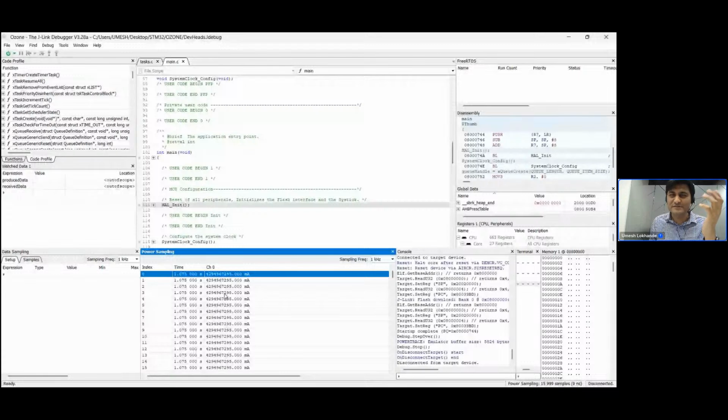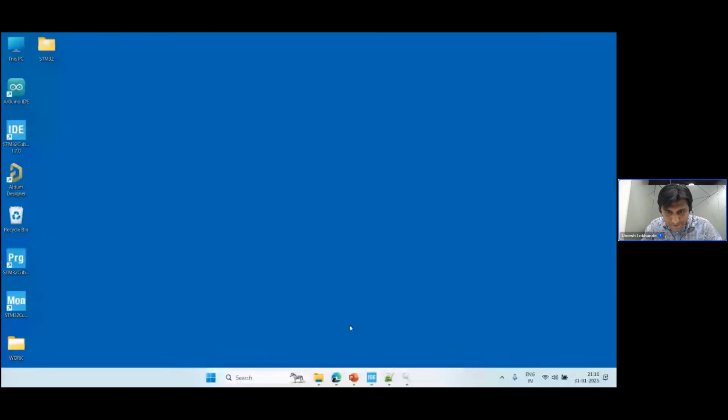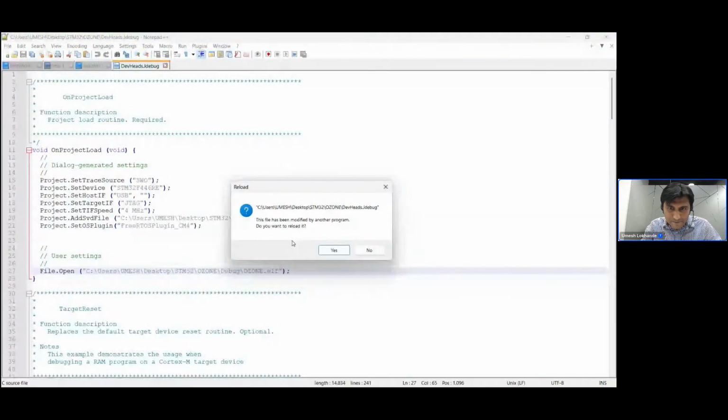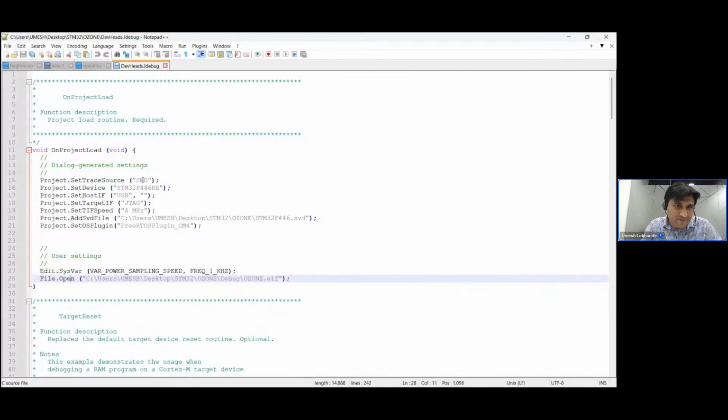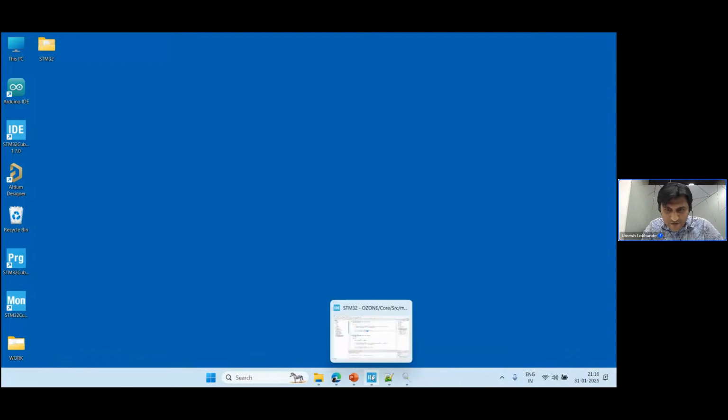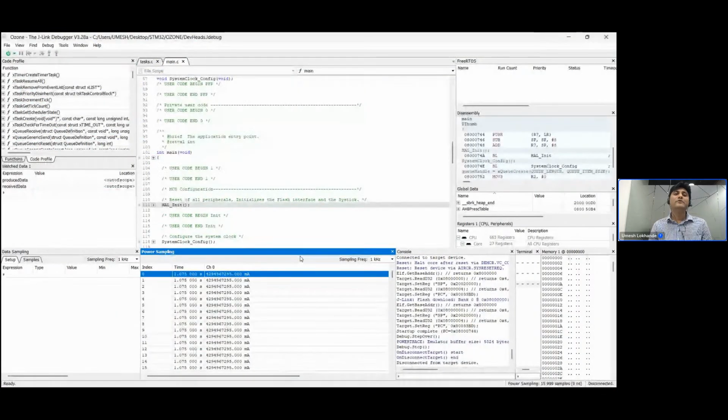And we talk about ETM, and when you use SWO for the debugging, if you look at the J-Debug file, we are using SWO traces, serial wire output. So this basically uses ITM traces. So it has nothing to do with ETM, wherein the reason why we have a limited capability is because we are using an on-chip buffer, right?